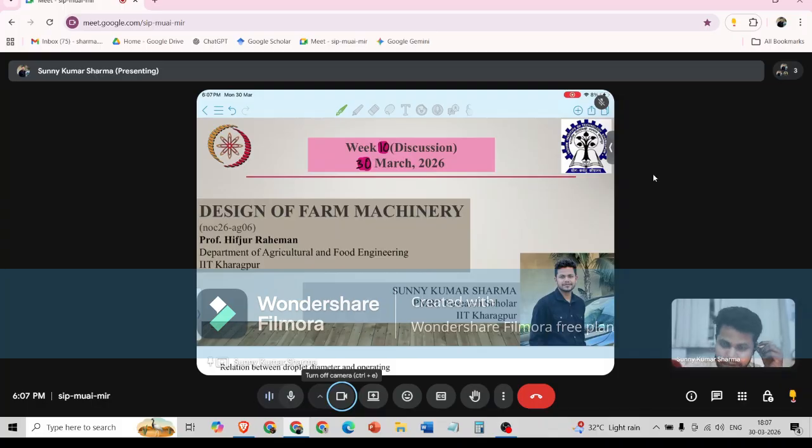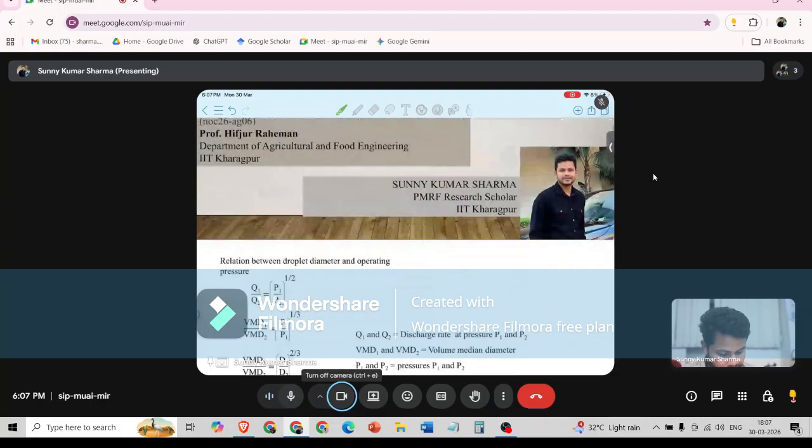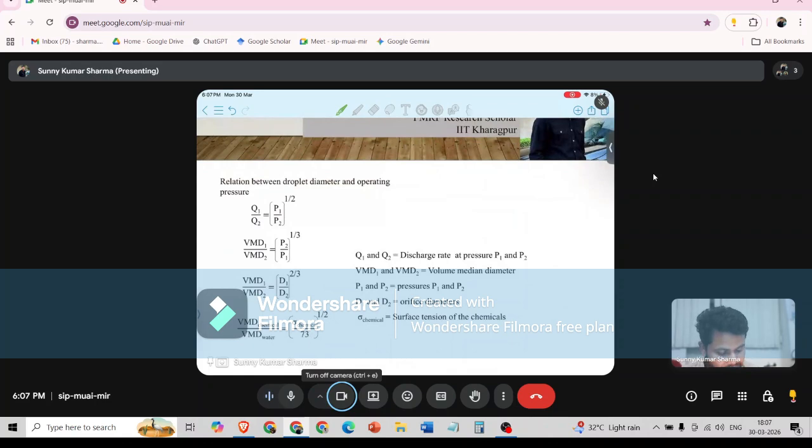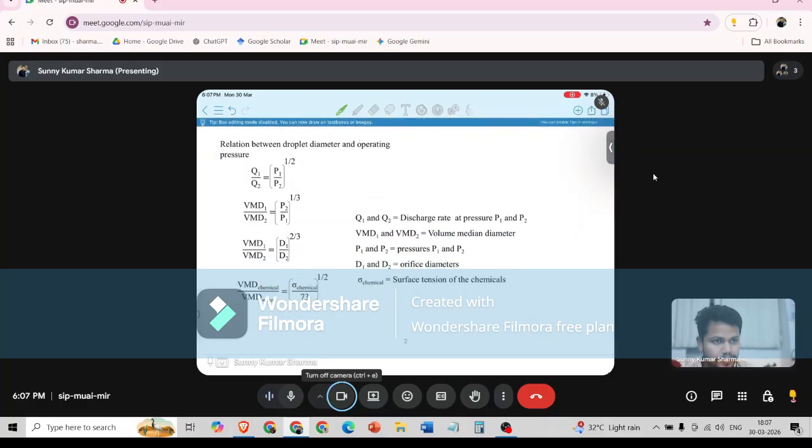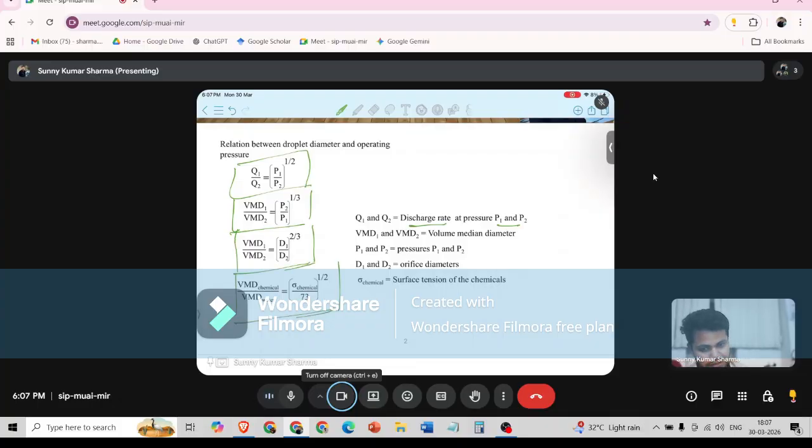In the last class, we discussed week 9, where we mainly covered the spraying part, the sprayer related numericals and theory. We saw the relationship between DMD, pressure and discharge, orifice diameter, and surface tension of the chemicals. So you must have completed this lecture. You can note down that the relationship between discharge rate and pressure is given by this equation. This is the relationship between DMD and pressure, this is between DMD and diameter, and this is between DMD and surface tension.